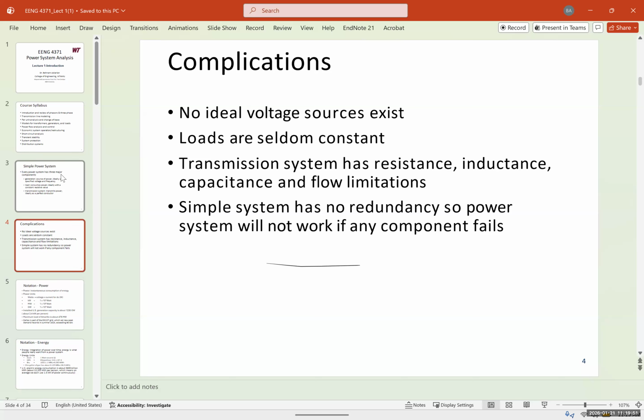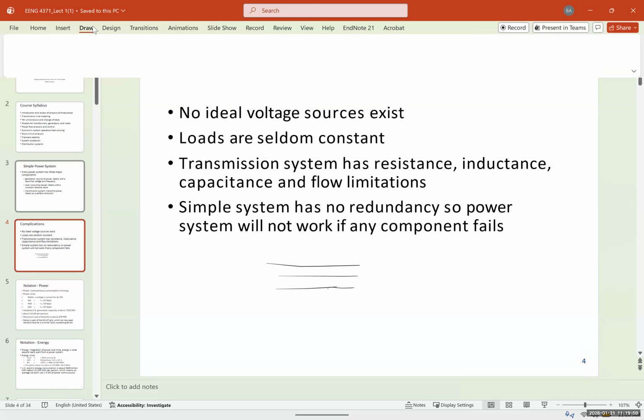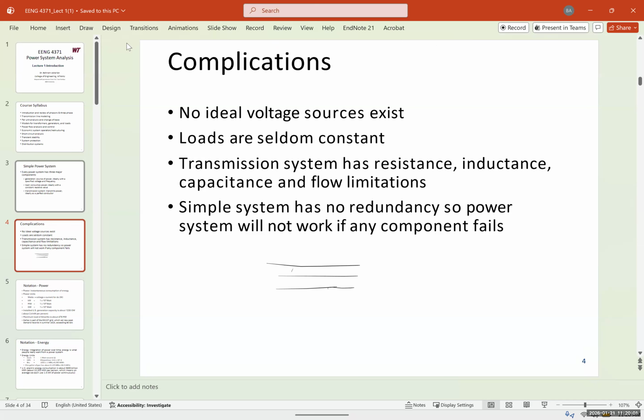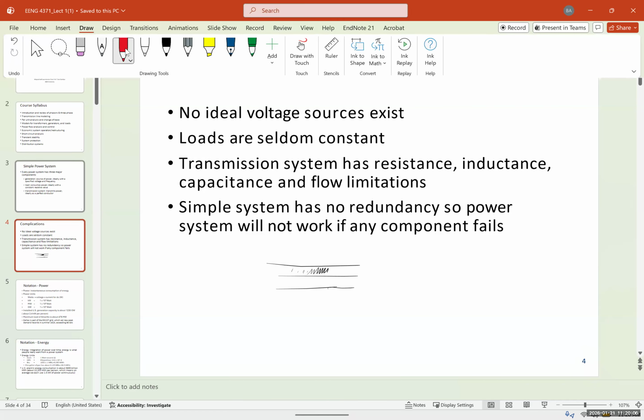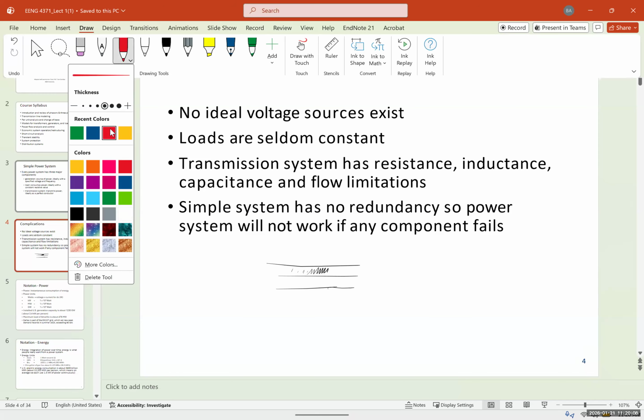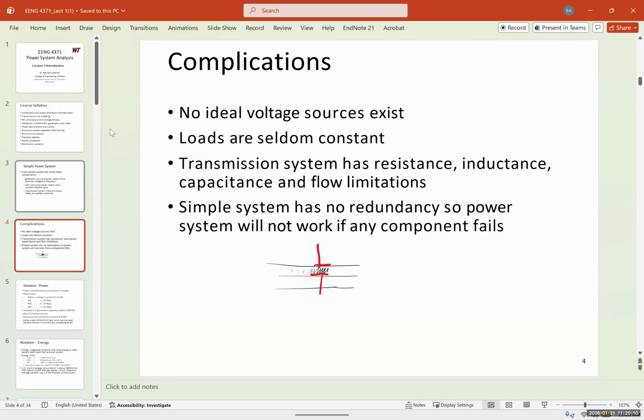If you have multiple conductors, wires, moving in parallel, the air between them acts like an insulator. And what you technically have here is a capacitor, okay? This could be the capacitor between the neutral and one of the phases. So we have capacitance on the line.